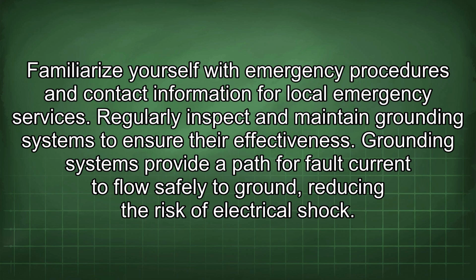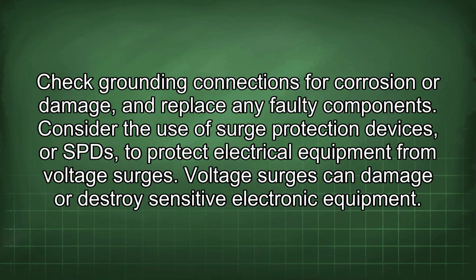Regularly inspect and maintain grounding systems to ensure their effectiveness. Grounding systems provide a path for fault current to flow safely to ground, reducing the risk of electrical shock. Check grounding connections for corrosion or damage, and replace any faulty components.